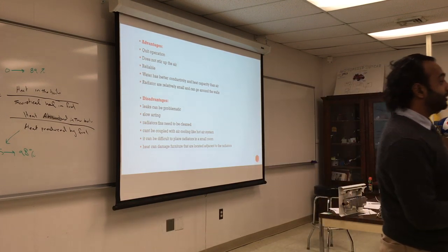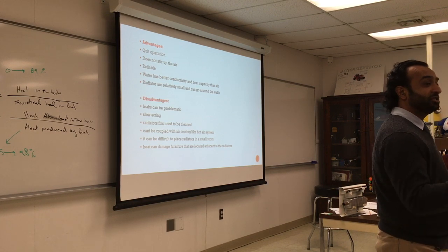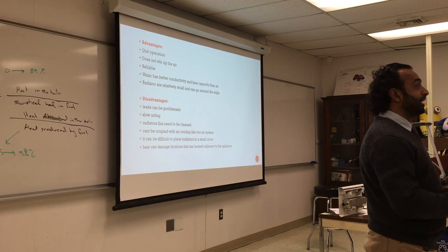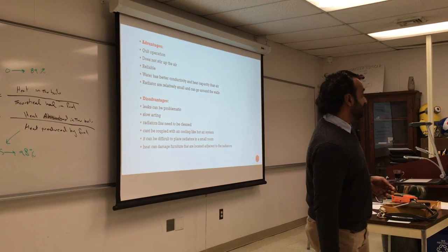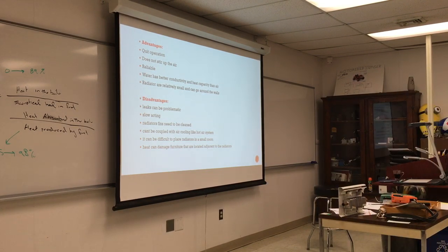You, again, probably won't remember that. Back in the days when you used to have those V8 engines that produce a lot of heat, over time, they tell you to flush your system every year, the radiator system. Otherwise, it will get clogged and the car will start to overheat. We don't have these overheating problems now because the engines are smaller. But if you have a V12 or V8, they produce a lot of heat and you have to have a huge radiator. It has to be cleaned. And every once in a while, you go and wash your radiator in the car. You go with a brush and take all the bugs out because, again, they block the heat.